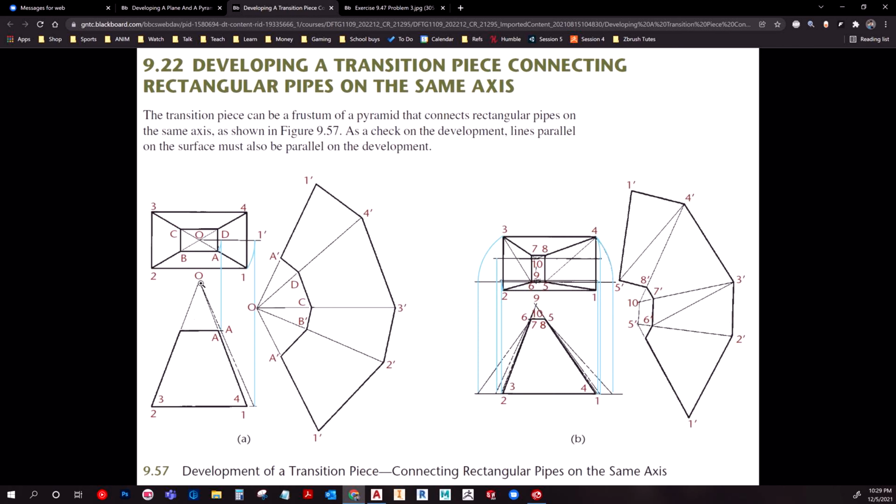You essentially draw a circle from the origin in a top view, snapping to the vertex. Depending on whether the shape is weird, it may be multiple sides or it may just be one, like in the case of this. And you do the same for the outside, which is what they're showing here. Then you extend a line down until you get to the line that these points reside on, which in this case would be the line A. Where that meets that line, you draw a circle to that point. And essentially this is the shape that you would use for over here.